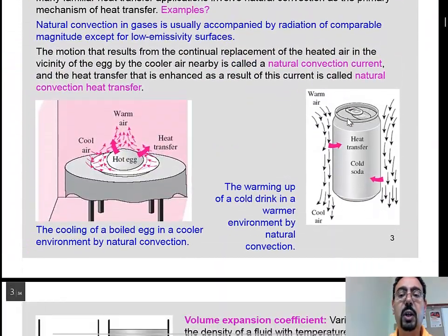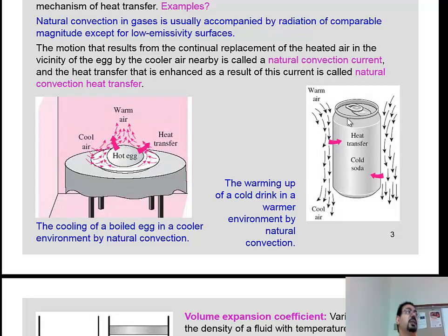So natural convection is basically just like forced convection, except that... so in convection, what was the deal? The deal was the first layer of air or fluid or crude oil, the next layer is conducting with the metal, with the solid, right? But in order to improve that conduction, we always would like to disturb this boundary layer. We always would like to bring fresh air or fresh liquid next to the wall so that it can increase the conduction. So convection basically works by moving the fluid by a fan or a pump or whatever the mechanism, so that you always change the layer next to the wall.